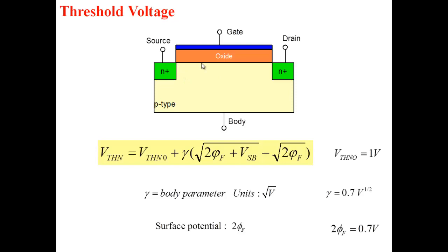The other freedom is the width of the MOSFET, perpendicular to this particular plane here. The width of the MOSFET is again under your control. Okay, so the width, again, there is a minimum size to how much width you can use. Okay, we will discuss that later on when we talk about layouts. So there is a minimum, technology will tell you the minimum that is possible. So there's a limit on how small a width you can use for a particular technology, how small a channel length you can use. Beyond that, if you want to increase, do as much as you want. Higher values are not a constraint. So voltages, you can apply what you want. Channel length and widths are all available here.